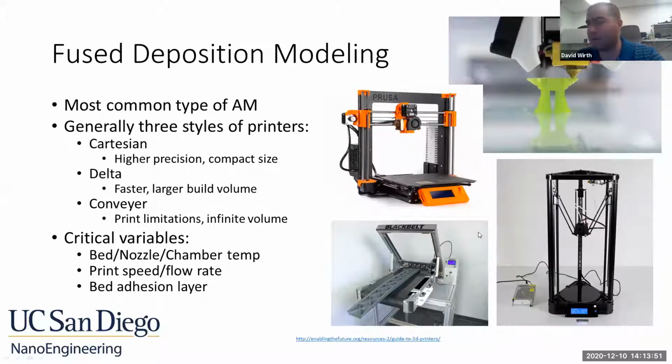And then these higher end printers are probably going to have an all metal hot end. Those can theoretically go up to 350, 400 C. And with that, you can print most materials. But some materials that have a high warping, such as ABS, polycarbonate, you really need a heated chamber for those. So that's another thing to think about. And I'll talk about that a little bit later. The other thing to think about is how fast can these things move, right? So as I said, the Delta printers are a little bit faster, so that's going to enable you to print larger objects in less time.